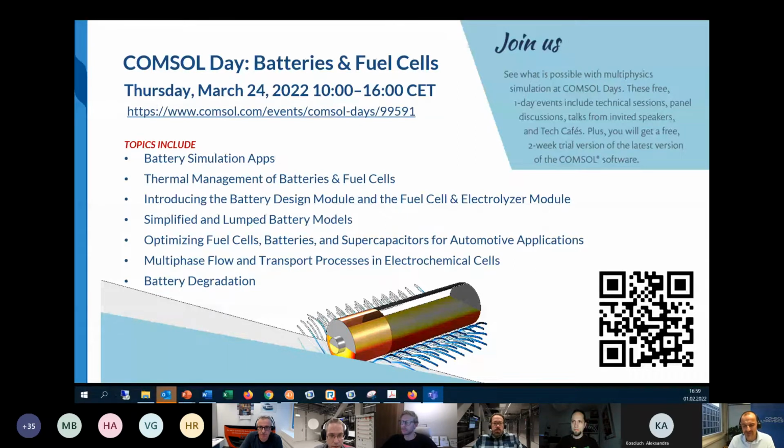optimization algorithms, and for simple cases, you could still also make a parametric sweep in at least a coarse grid through your parameter space to identify if you have somewhere a global minimum, which would be desired for an optimization algorithm, right? But today we can use the uncertainty quantification module to really detect the correlation between our choice of parameters. Okay, so there are some ways to test essentially how valid the optimization result is that you obtain.